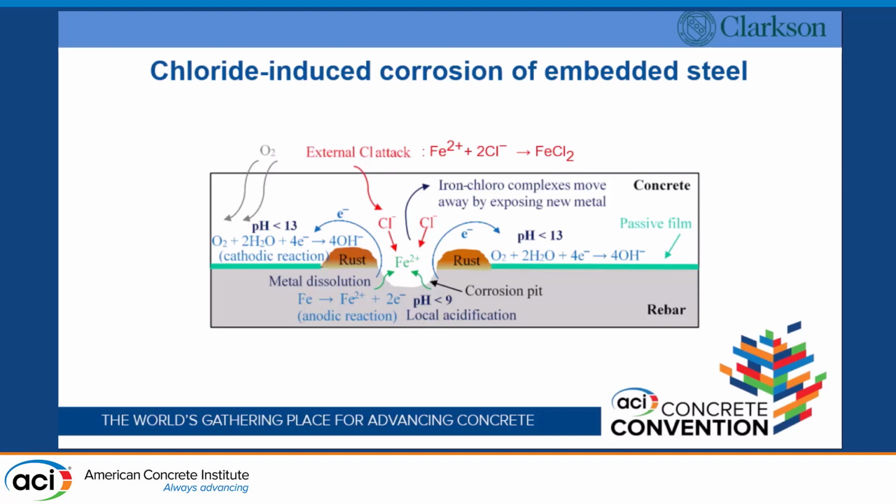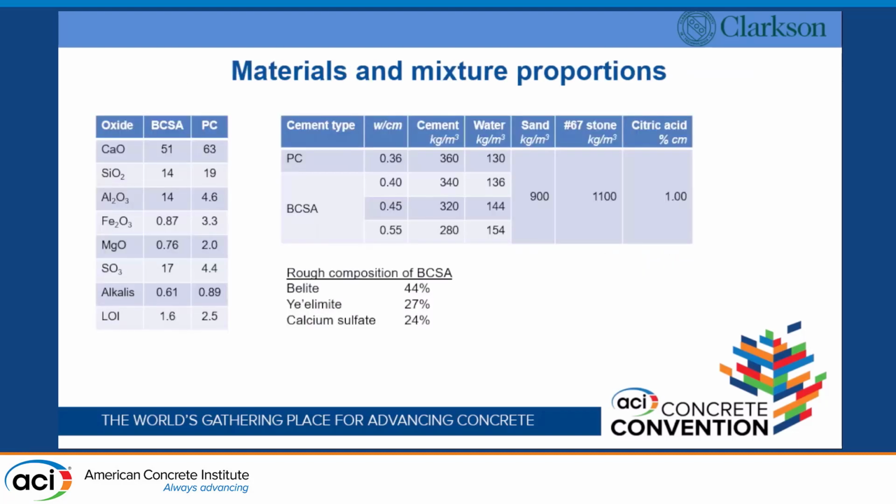I think we're all pretty familiar with the chloride problem. The chlorides go into the concrete, they depassivate the steel, and they corrode the steel; corrosion products are expansive. This is actually the biggest problem for concrete infrastructure globally, so we really need to tackle this, and we need to understand what's going on with the material before we can apply it at broad scale in steel reinforced concrete.